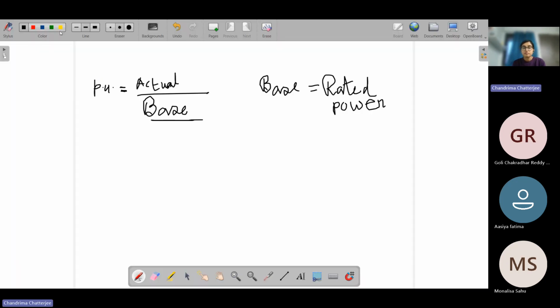Let's then solve it. As we are talking about active power, it doesn't matter at which distance they are asking. It could be 250 kilometer, it could be 400 kilometer, it could be 500 kilometer, doesn't matter. Because active power doesn't get affected with the distance. So we don't have to worry about the X here. This information is not required here. This is just an extra information. Because in active power expression, we don't need to put the L value, X value.